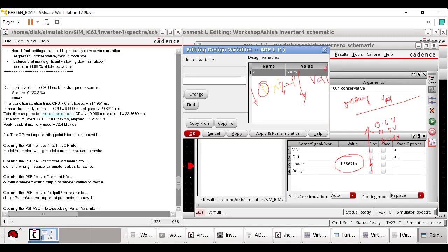So what we have done so far today is that we have talked about the inverter circuit in the case of various leakage control techniques. We have used a technique of stack, a technique of sleep, stack sleep, high threshold, and reducing the VDD. Then you can always find the power dissipation and delay, multiply them and see the PDP of the circuit, which is called power delay product. You can see whichever is less is a better technique. So these are the circuit techniques. There you see the impact on delay, the impact on dynamic power, and the impact on the size of the device.